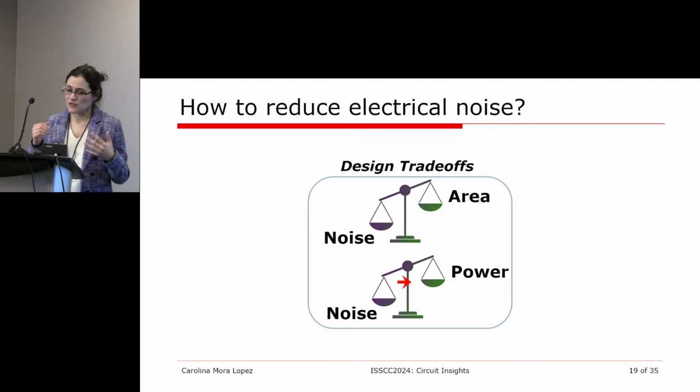To give you an example, in applications where you want to have many amplifiers to read many electrodes in parallel, this is important, for example, for neural interfaces. You want to record as many signals as possible at the same time, so you want to have many amplifiers. And here, area and power are going to become your most important parameters.